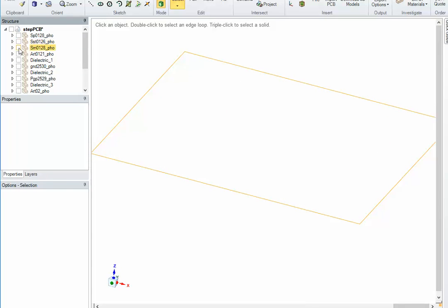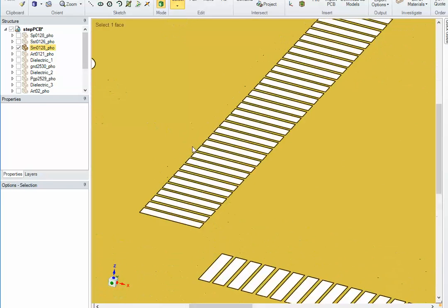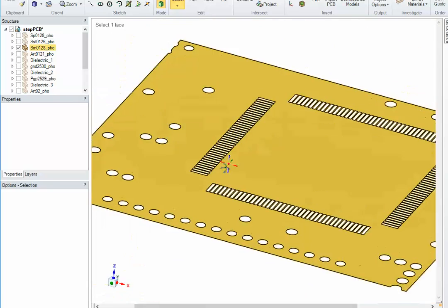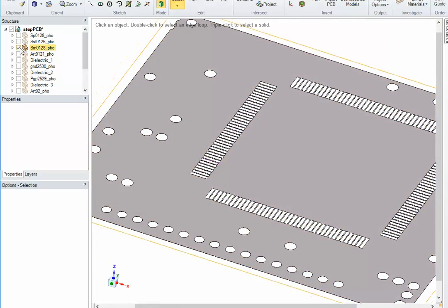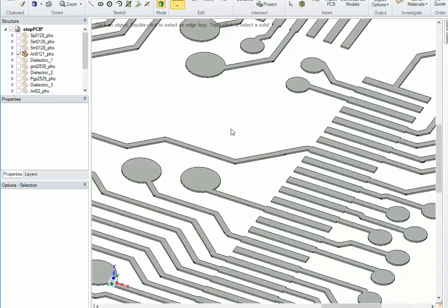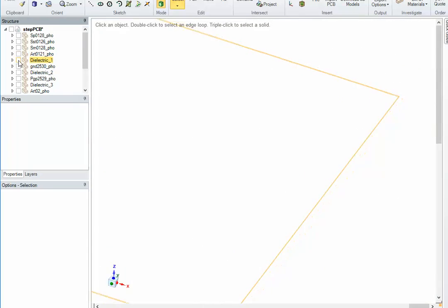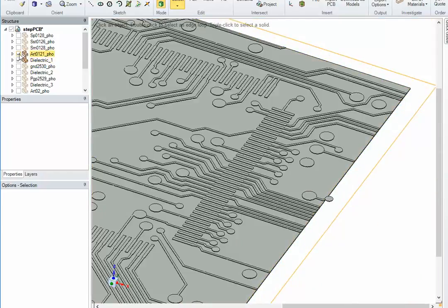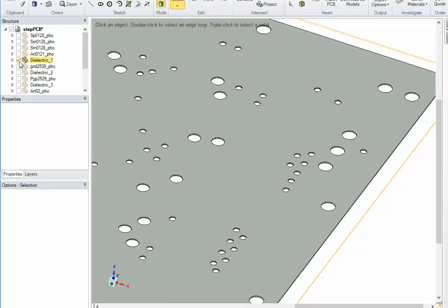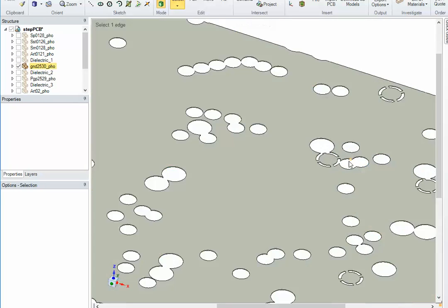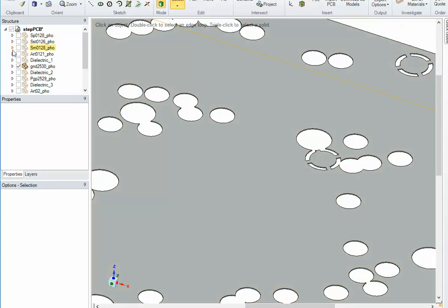Your solder mask, now this is opposite. So remember, it's just the pads in the Gerber file. What ACE 3D has done is it went ahead and created a negative, which means the opposite area. There's the metal for the top layer. Here's your first dielectric. Then you've got your ground. And see, again, this is where it's been made negative. So these thermals now have been reversed.